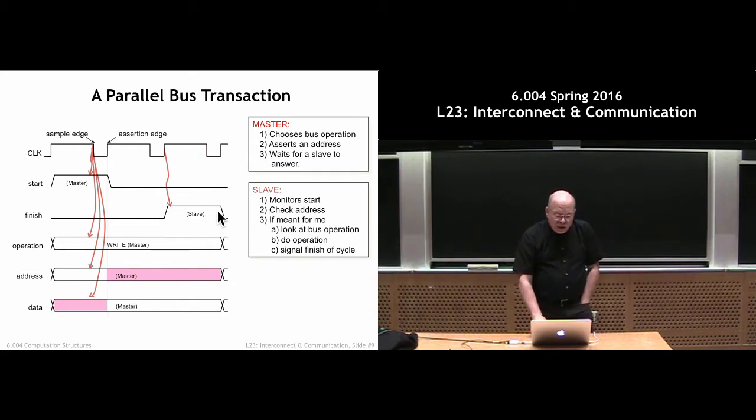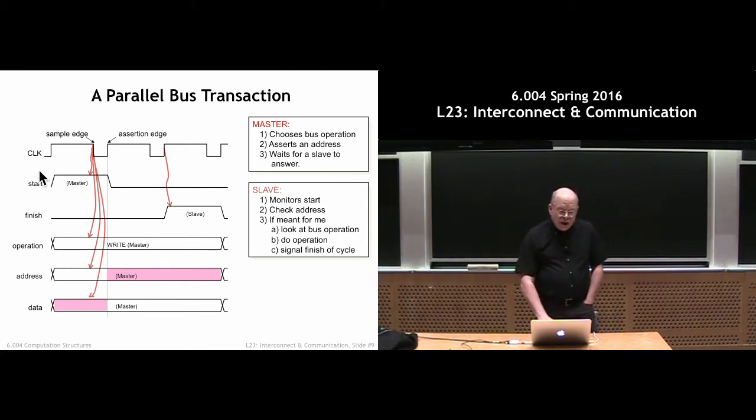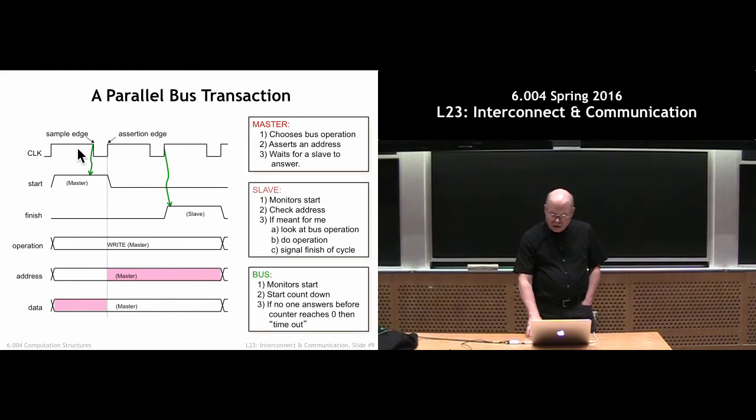The whole issue of carefully separating when you put a signal along and when you looked at it took care of a lot of issues of clock skew, so that not everybody sees the same clock edge. So if we all did everything on the rising edge, it may be that if I'm the master, I will have started to change my signal before the rising edge reaches you, some number of nanoseconds later, and you're still trying to look at the last signal on the bus, right? So this notion of separating when you look and when you change the signal was important to make these protocols work in the 100 megahertz timescale.